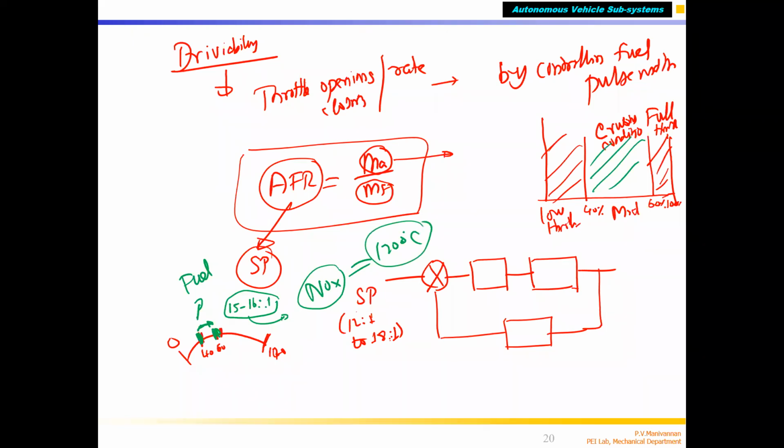But in a thermal machine, if you burn all the fuel, you get a higher temperature inside the combustion chamber, correct? Here the fuel is burning, and the higher the temperature, the more pressure will be acting down, pushing the piston down, which is converted to torque. You will get more torque, correct? So thermal efficiency is more, meaning the temperature is more and all the fuel is burned. In that case you get more torque, every advantage, except the only thing is NOx, nitric oxide.